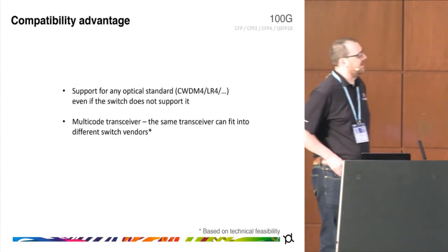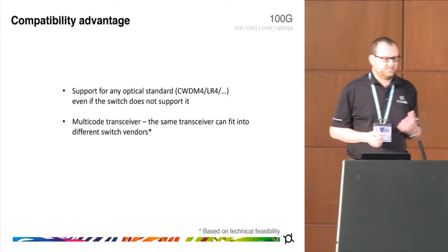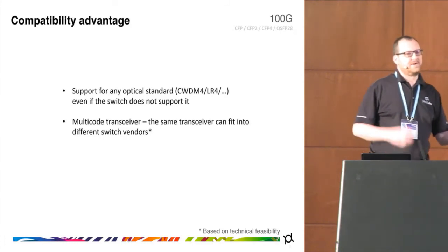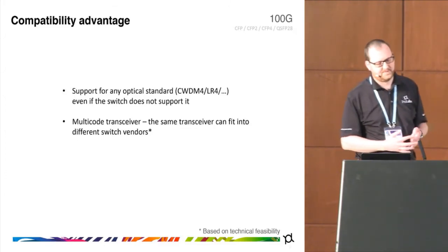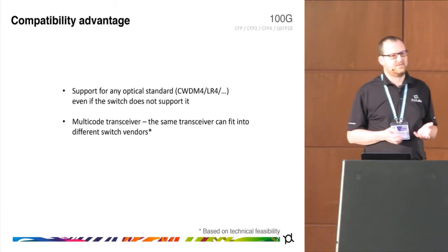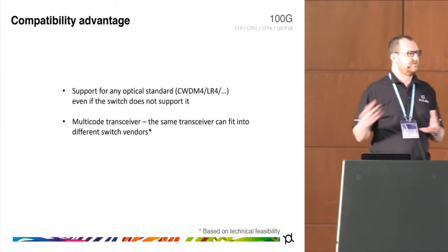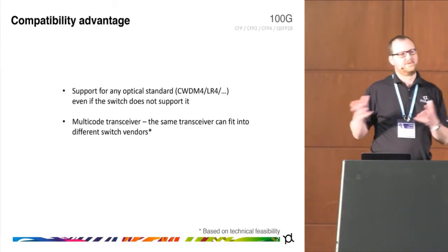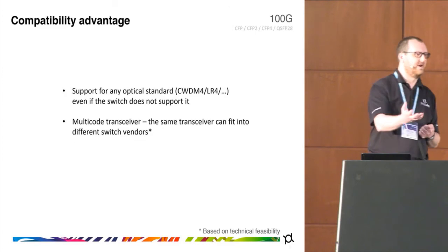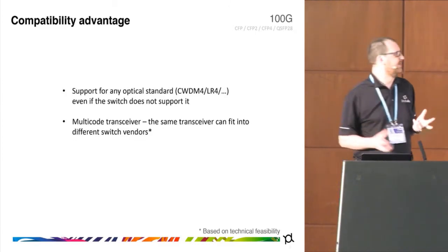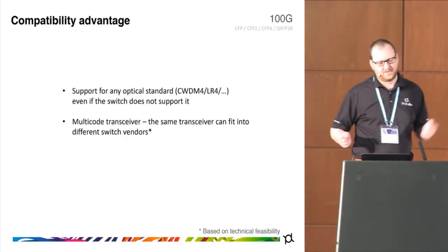But the interesting part is about compatibility and what you can plug into what. So if you've got CWDM4 interfaces, you can't connect them to LR4Ls, even though the distance is the same, because it's using different wavelengths. And this is one of the problems that we see in the industry, is that some vendors of switches and routers favour one technology over another and might not offer all of the different options. You might be stuck with an LR4 option, or you might be stuck with a CWDM4 or an SR4. So that's where we come in, with the options that we can provide: all the different solutions with all the different vendor compatibilities.